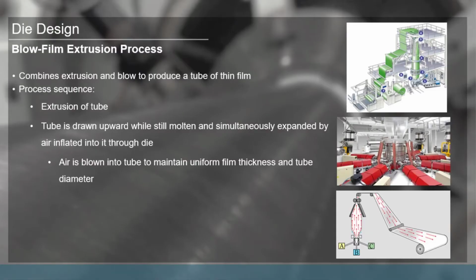Blow film extrusion process is just a variant of this. Basically, you have the polymer melt extruded out, and then you run it through the blow filming process, and you can actually do extrusion of tubes and all these things using this particular technology. And this is again a variant of blow molding, which can make rigid parts, but this could be more flexible parts.